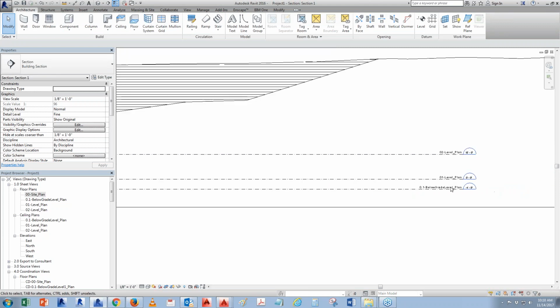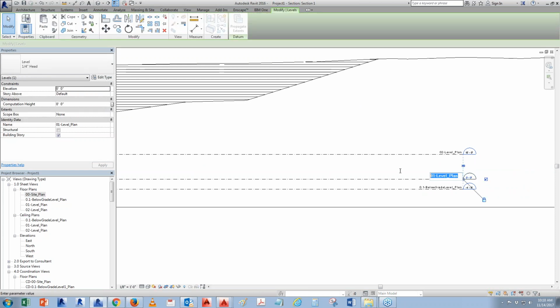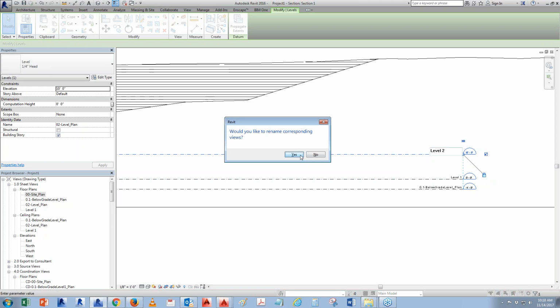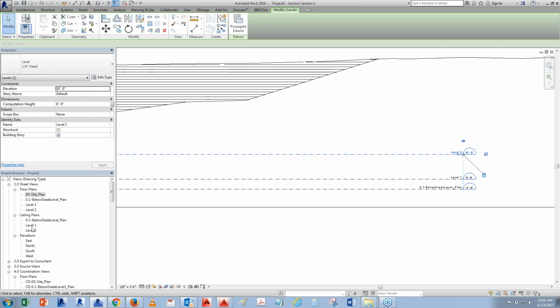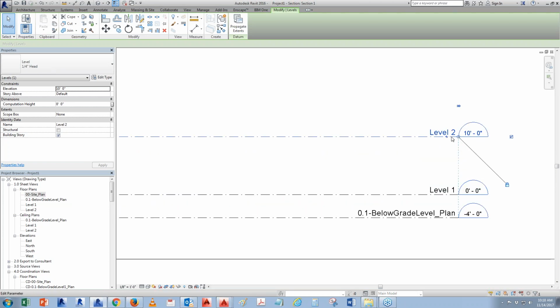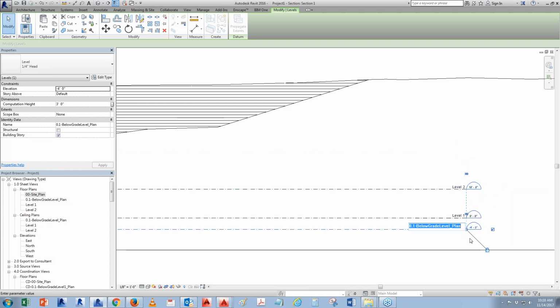So what you want to do is that whenever I establish any of my Revit projects, I always like to put this level 1 and then say yes, level 2. Now, the reason why the template itself is a little bit messy is that whenever a user renames the stuff, it will rename your elevation right here. So this is why I tell the user, you always create a source view. It's the same reason that somebody should not be messing up with your elevation level. So it should always read level 1, level 2, et cetera. But this one apparently didn't do that, so that's fine.